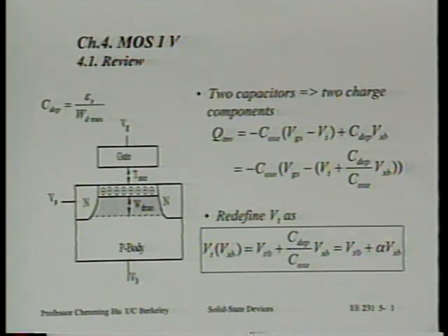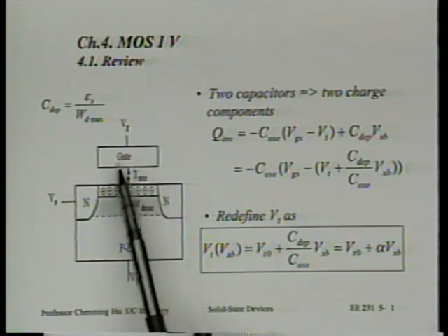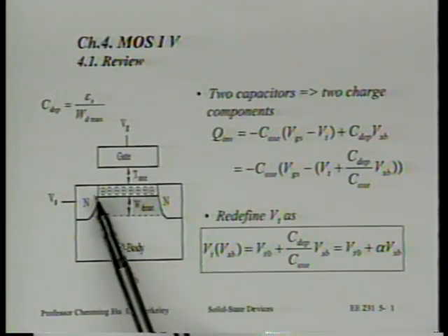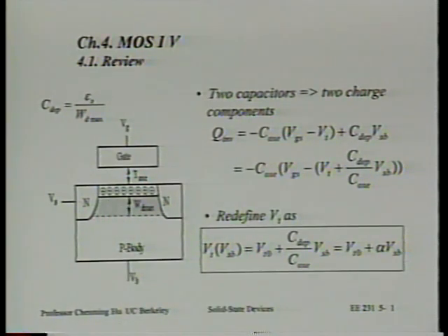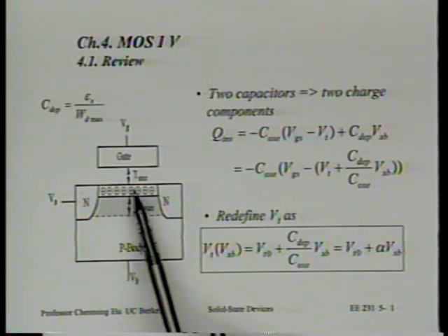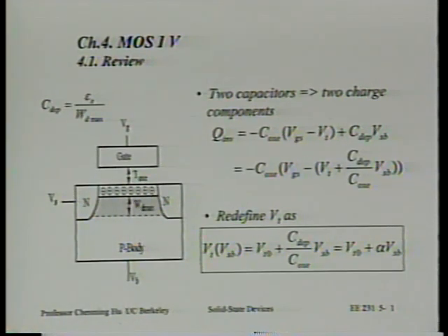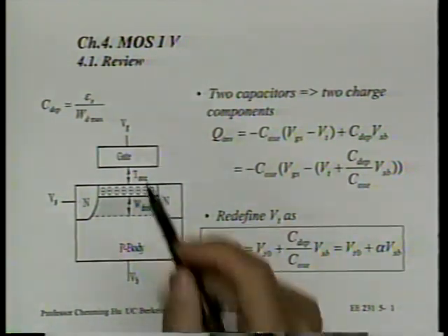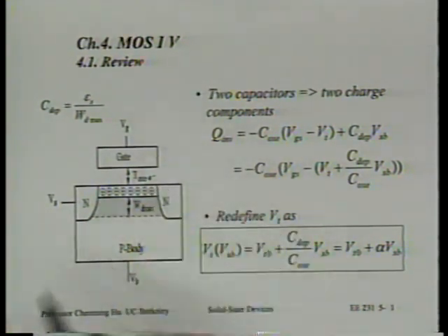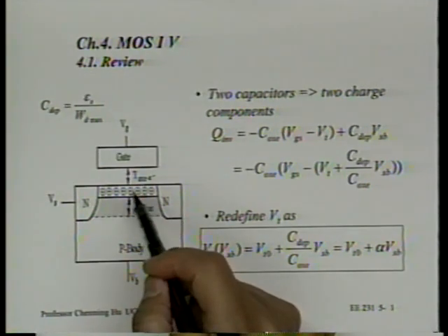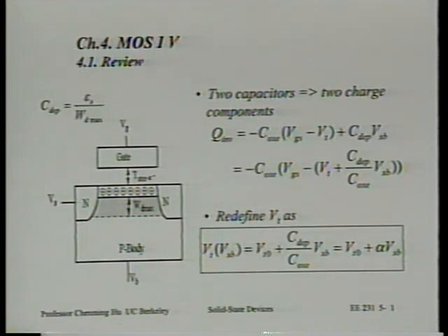We'll see this first twist in the first slide here. I want you to take a look at this cross-section. We have a gate. We have an inversion layer. Let's just visualize the inversion layer as a very thin sheet of electrons, all right? To the extent it has some finite thickness, we can incorporate that fact into the thickness of this T ox. Is that right? In fact, the subscript E stands for either effective or electrical. In other words, it may not be just the physical thickness of T ox. We might have already incorporated some of the thickness of the inversion layer in it, right?